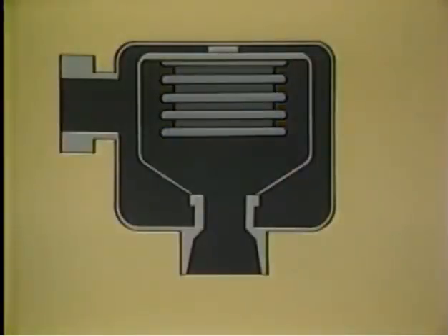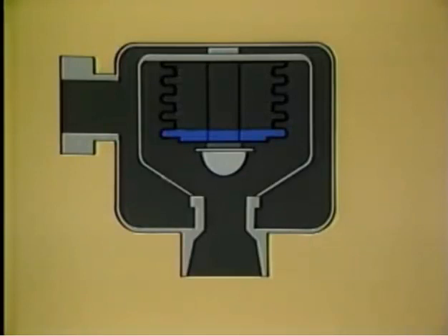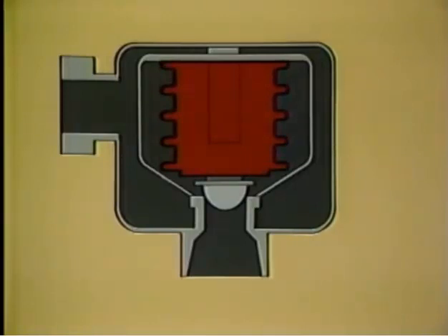The bellows contains a liquid charge which vaporizes at or slightly below the boiling point of water. One end of the bellows is secured within the body of the trap. The valve is located at the opposite end of the bellows. When the bellows charge vaporizes, the pressure inside the bellows increases. A sufficient increase in this pressure expands the bellows to seat the valve.